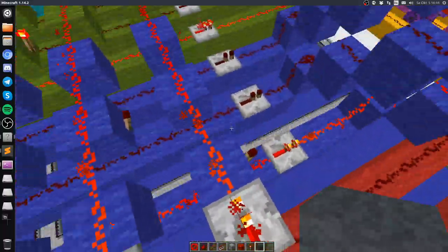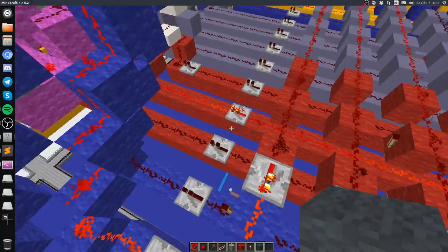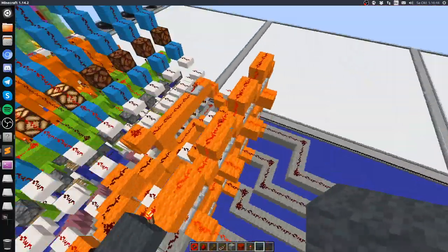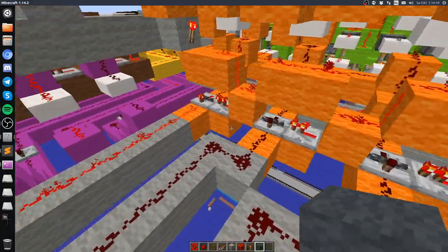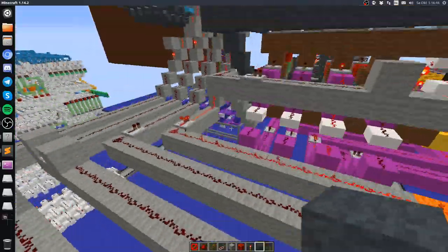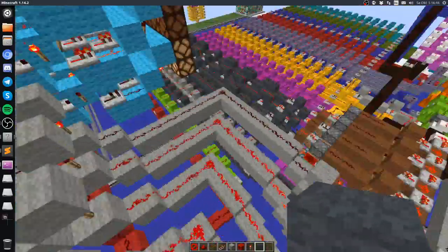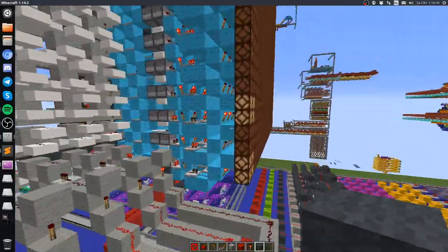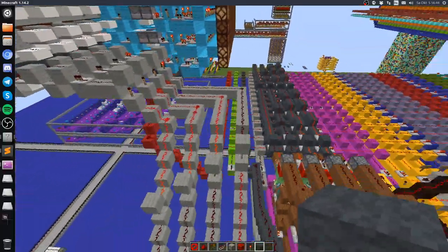You should initialize your registers with whatever value you need, because you cannot be sure that it's the correct value. And also cannot expect that this one actually stores the correct value. It totally can be random stuff like 1 in this case. And we don't want to write 1 to this display or something.